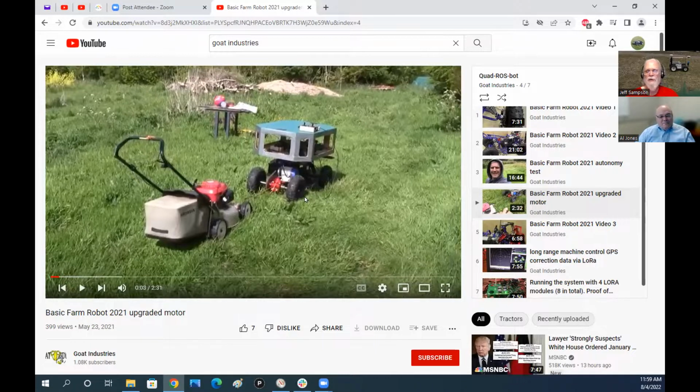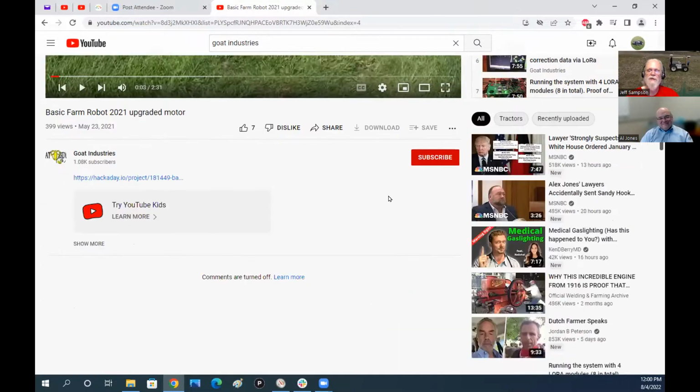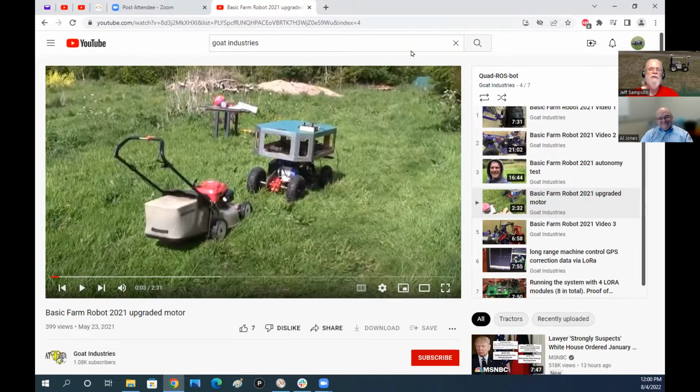And the thing was, in the first video, he said, okay, look at it. It's got this electric motor, and on the back, it's got a sprocket on the axle. It's got a small sprocket on the motor. He says, boy, that's a lot of reduction. But then when he goes to run it, it looks like it'd go like 50 miles an hour when he cranks up his remote control. And instead of putting a new motor on, he'd be better off putting an extra level of gear reduction between his motor and his back axle. So put an extra shaft with a second chain reduction on it. He probably would have been better off. But anyway, he has some interesting stuff there if you want to dig through it and see.